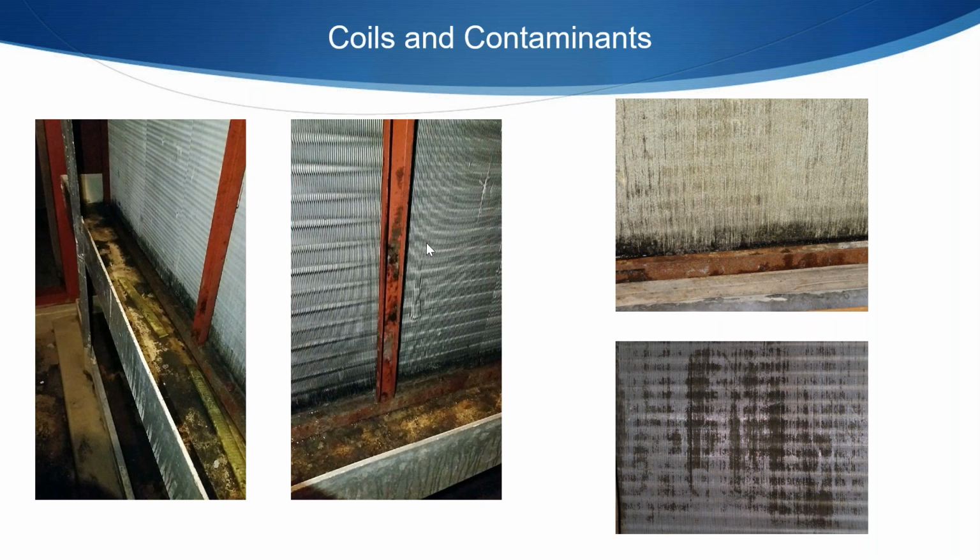So all of that is absolutely important, both to indoor air quality and to overall building energy and maintenance issues. But this is also a breeding ground for other things that can be very dangerous, like bacteria. And despite having filtration downstream, we have run into some clients that had significant enough mold buildup on their coils that when they were changing the filters, they knocked mold into the system. And it was unfortunately in an operating room space, and there was loss of life. So these are things to be aware of when you're considering the use of UV in a system.